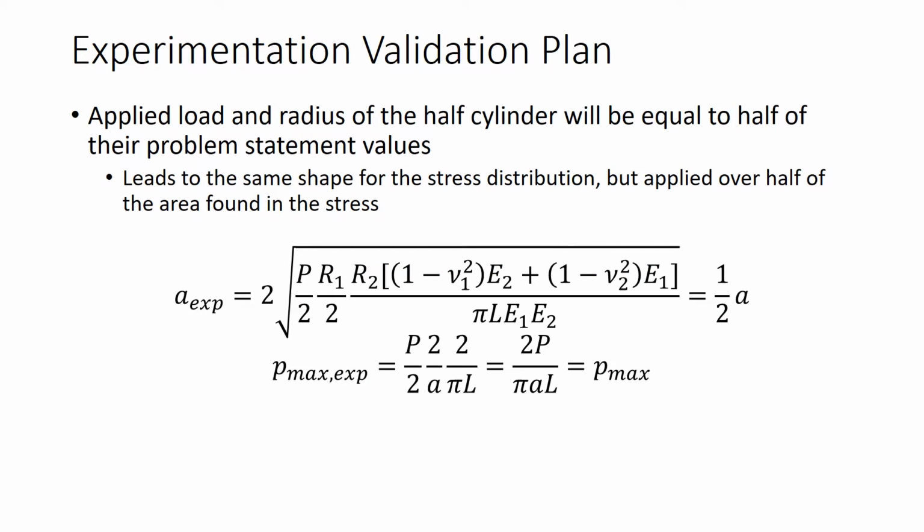Due to the large size of the wheel used in both the stress analysis theory and in the finite element analysis, practicality dictates that a smaller wheel be used. In this case, the half wheel will have half the diameter of the wheel previously used, but maintain its original width. This would affect the overall stress distribution, but by also halving the magnitude of the load, the magnitude of the stress distribution will be maintained, but the area of contact will be halved.